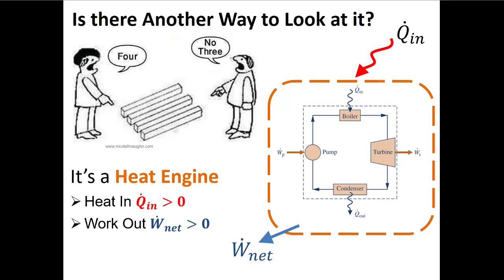But it doesn't quite tell you this. Right around this point, it starts to say, don't worry, we'll just take everything as an absolute value. So net work in the textbook is turbine power minus pump power. But to do that, you have to make pump power positive. So my suggestion is always going to be work all of these terms out with the first law and add them up. Let the first law worry about what the sign is going to be, right?